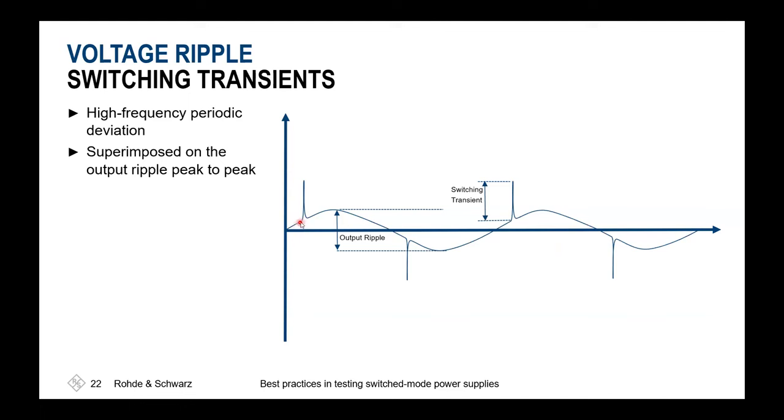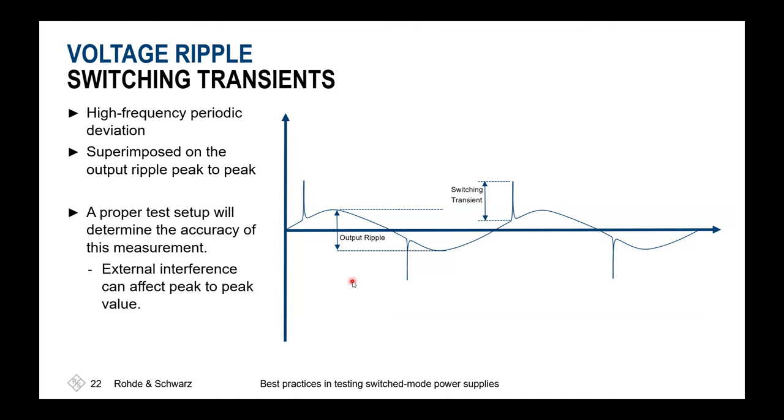The bad thing on these peaks is these are having steep edges. Steep edges mean they are inducing a wide frequency spectrum. And if your probing solution, we'll talk about later on, is insufficiently chosen, so you are having a lack of bandwidth, in that case, you might be unable to see the full beauty of the peak, and thus you might have an underestimation in your pre-investigations before you go to a customer site doing measurements, maybe also at the EMI lab. And this could lead to some headaches when you see, okay, what's coming up there and where it's coming from.